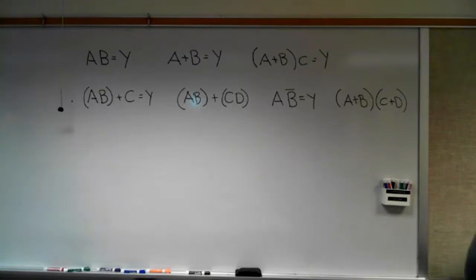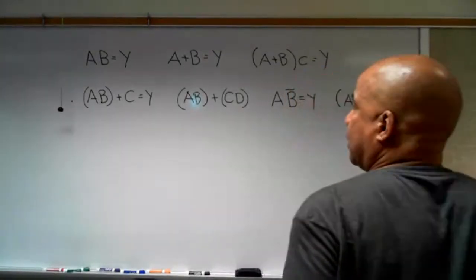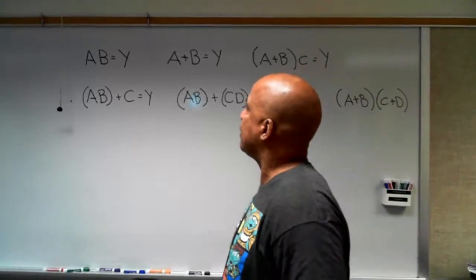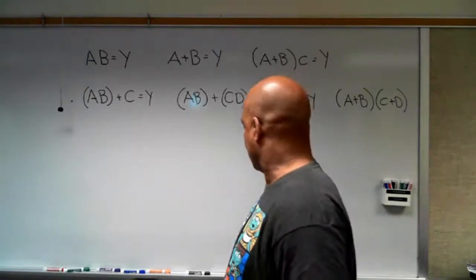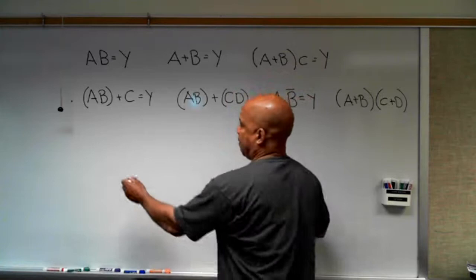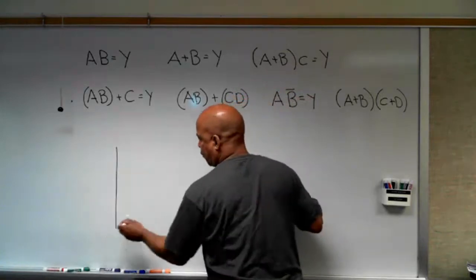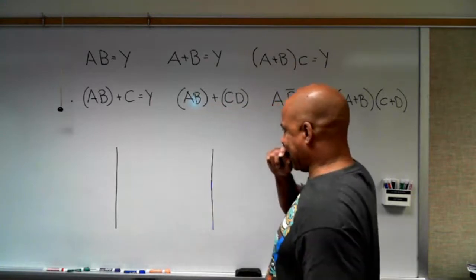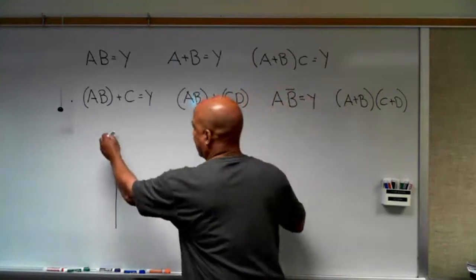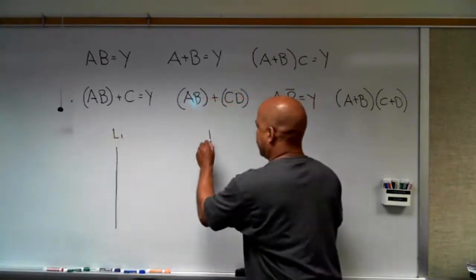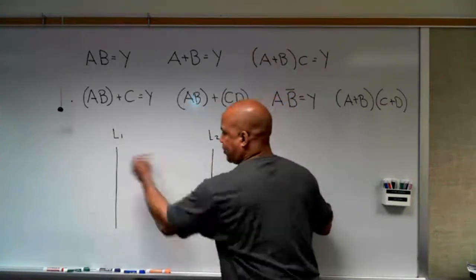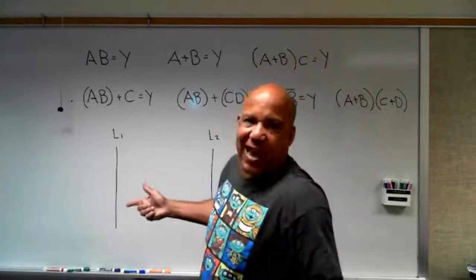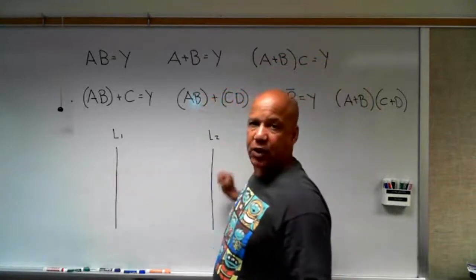All right, so we have these Boolean expressions, and we want to implement these expressions in what we call a ladder, a control ladder. And so we mentioned that the way you can think about control in an electrical ladder is you have these two vertical wires, and instead of having a power source, we just have what we call line 1 and line 2. And when I bridge this with a wire or with some symbols, if I have a closed path, then for now, just think of current flowing from L1 to L2 if there's a complete path.